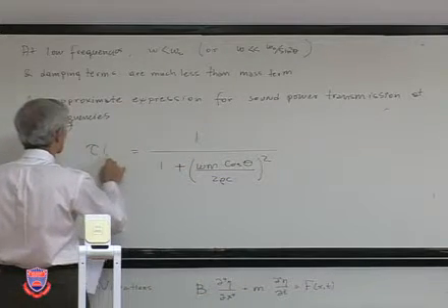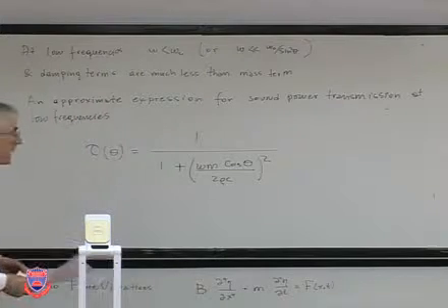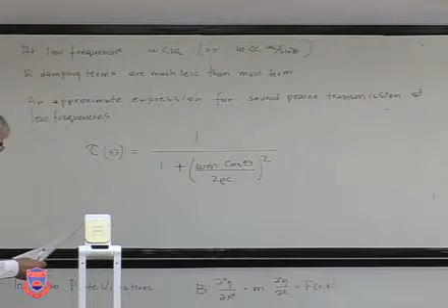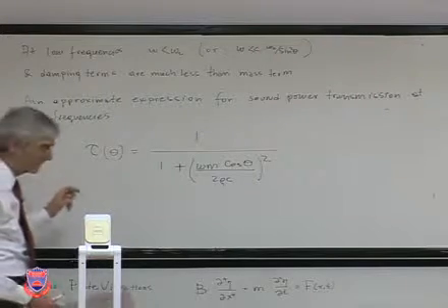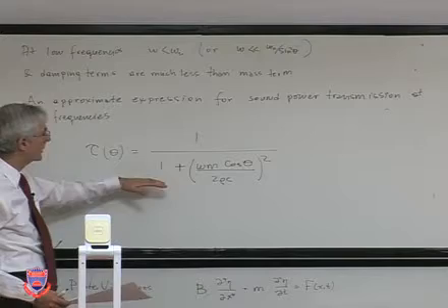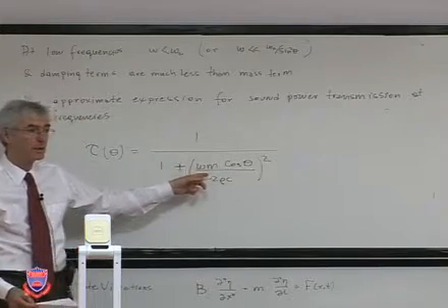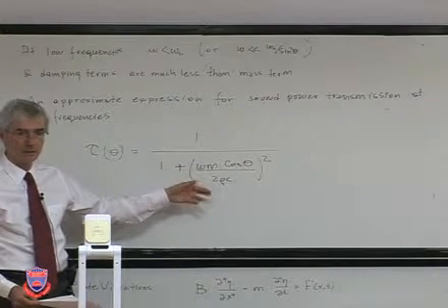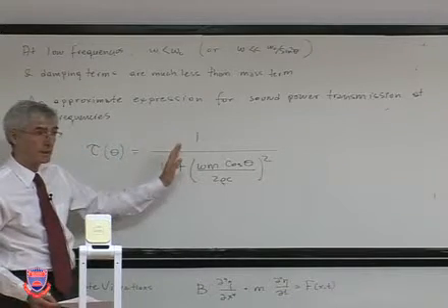Because of the angle, we also say it's an angle-dependent transmission coefficient. Now you can see what we're talking about here: at low frequencies, what is most important is the mass, not the stiffness, not the other properties. So it's the mass and also the angle at which the sound comes.